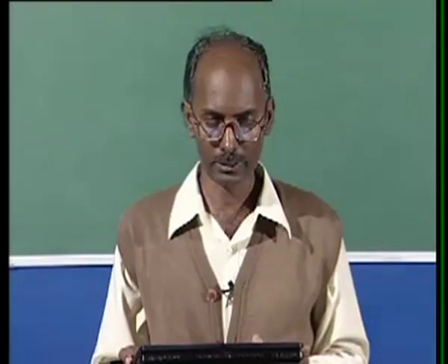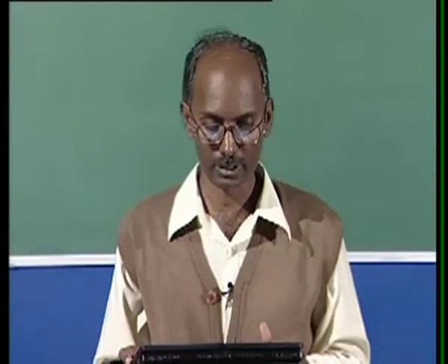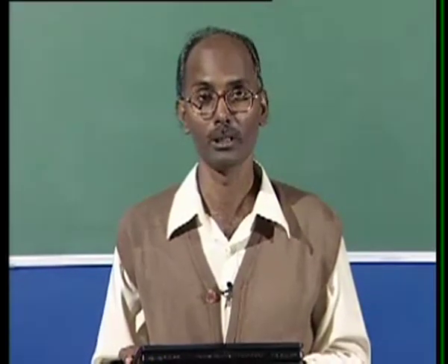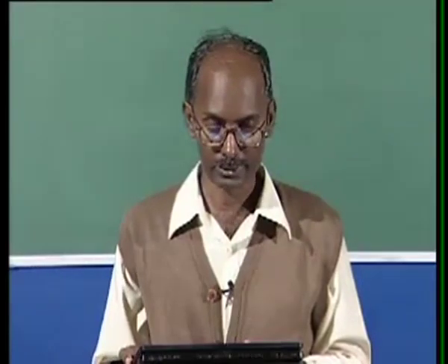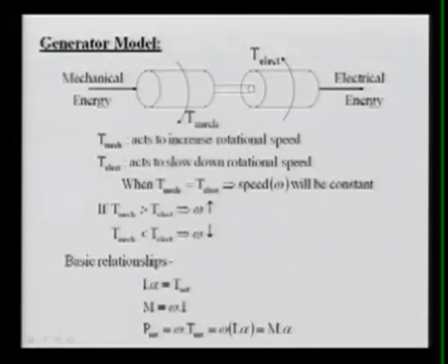Modeling. Now let us model another very important component in this load frequency control, that is the generator. In the generator modeling, we can understand that this is your mechanical power or mechanical energy input through the turbine, which is rotating. Here the torque is developed, and that is called the mechanical torque T mechanical. Now on the shaft, the electrical generator is connected, which is giving output in terms of electrical energy.